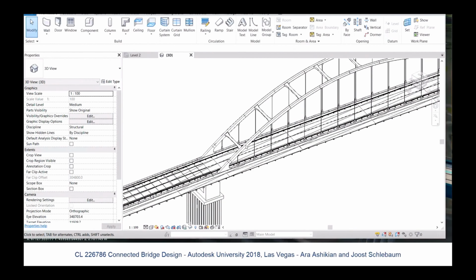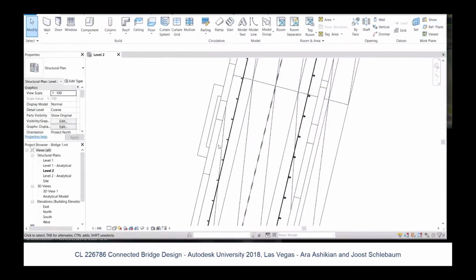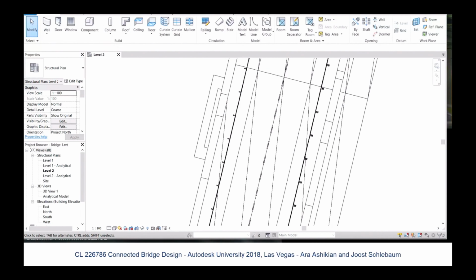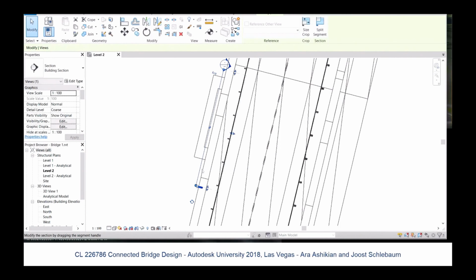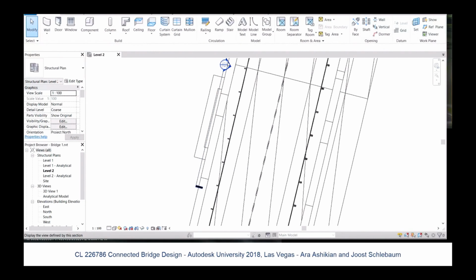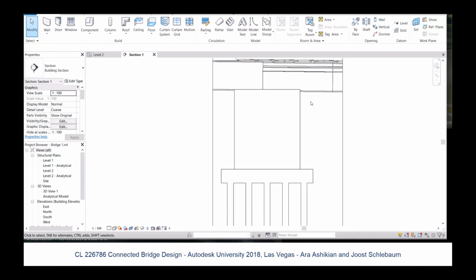When you click on all these components, all the parameters are going to be available in Revit. So you can do all the back end, which is probably the most important part of BIM, using that information. Here, I'm just going to quickly go in my Revit model and put a section view on the pier, on the support of the arch, just to show that. And again, it might be a different team. You might have the bridge team in InfraWorks, and a different office with multiple people using Revit collaboration, doing rebar and all sorts of things at the same time.